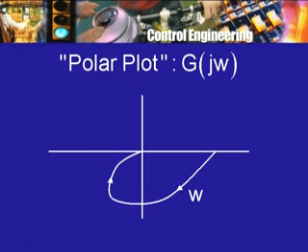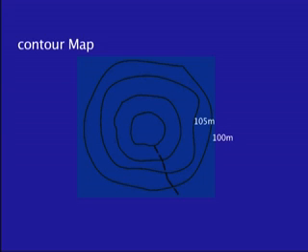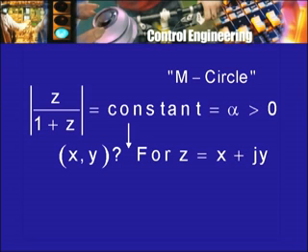We have the polar plot and we have a set of circles, then we can think of tracing the change in the frequency response as omega increases from 0 upwards, and for the intersection of this polar plot with the various circles, because on the circle, just as on the contour map, along the contour map I have the altitude labeling it, for the M circle I will have the value of alpha that will appear alongside it, and so from this one can read out the change in the overall gain as a function of frequency, and then if necessary, of course, one can plot it.